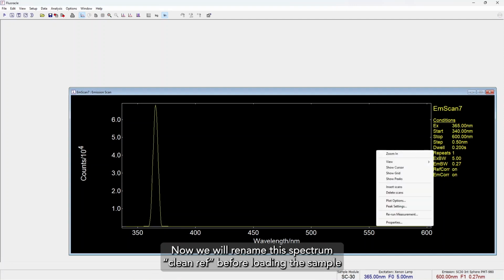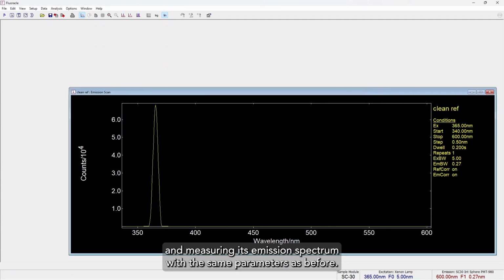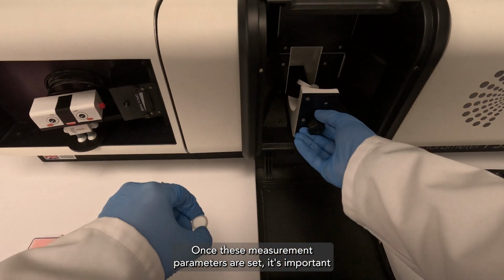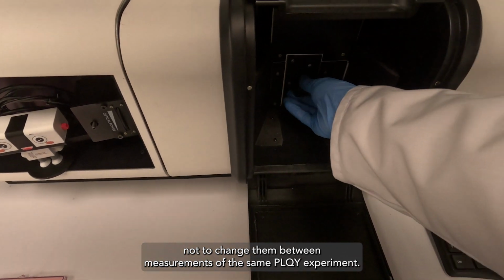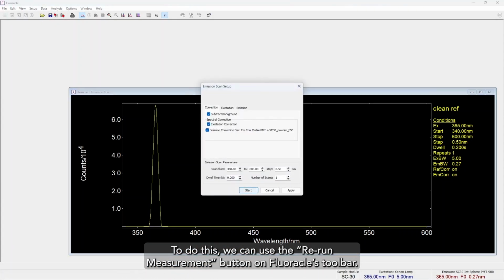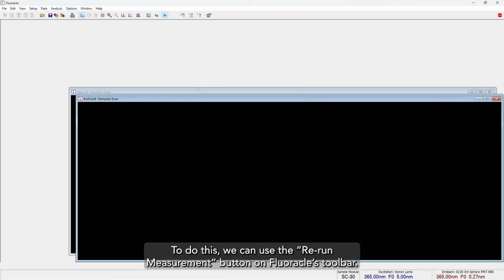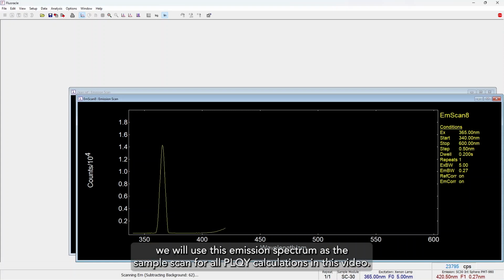Now we will rename this spectrum Clean Ref, before loading the sample and measuring its emission spectrum with the same parameters as before. Once these measurement parameters are set, it's important not to change them between measurements of the same PLQY experiment. To do this, we can use the Rerun Measurement button on Fluorical's toolbar. To test the effect of cleaning reference plugs, we will use this emission spectrum as the sample scan for all PLQY calculations in this video.